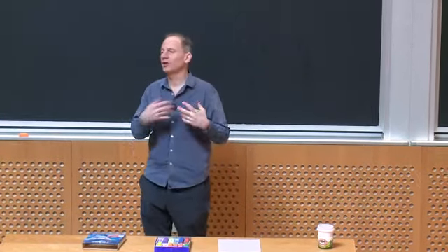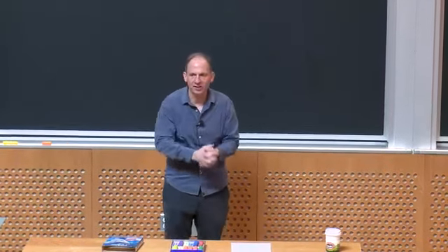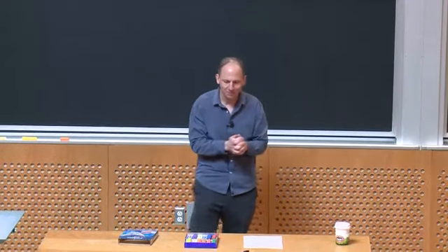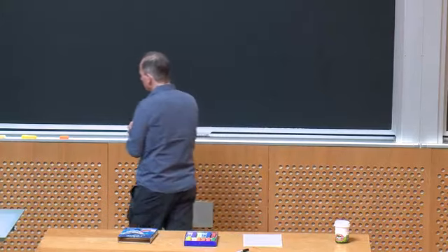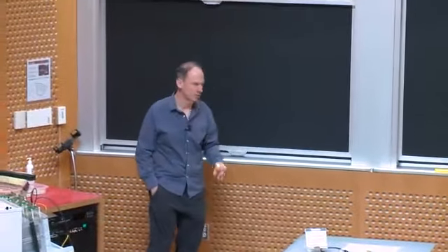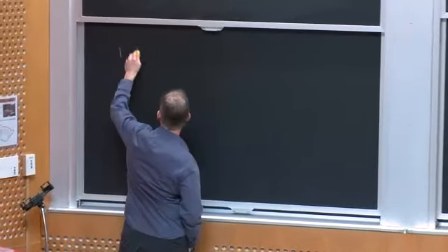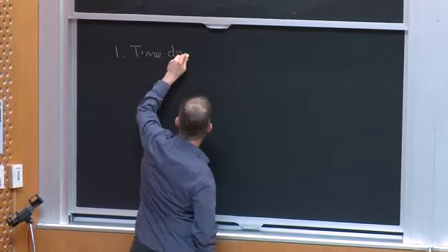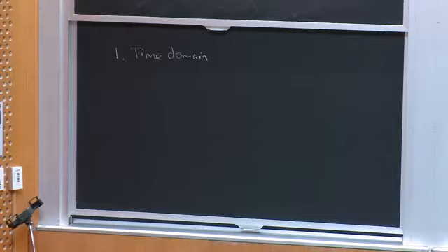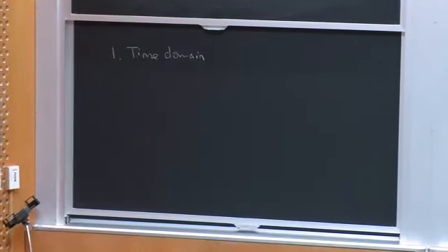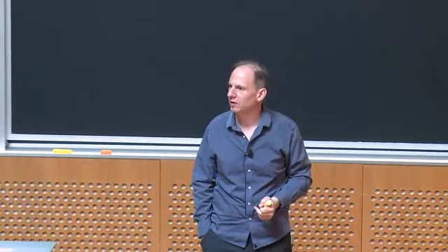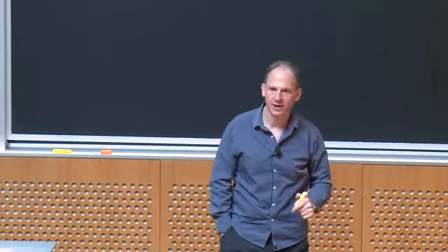And we want to suppress it maybe to meet some application desire, but we might want to suppress it also because we're not allowed to sell something that you plug into the wall that has too much ripple. Okay, so if we think about it, there's kind of two flavors of specifications we often have to meet. One of them is in the time domain, right? If I'm developing a power supply, somebody might tell me, oh, look, I'm only going to allow you to have 20 millivolts, either peak or RMS, of output ripple, because we want such and such a level of noise in our output, right? And that's one kind of specification you might need to meet.